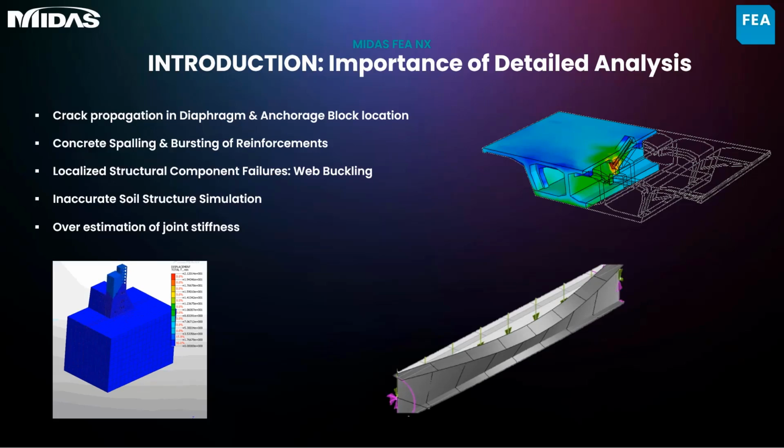Inaccurate soil structure simulation. In Southeast Asian countries like Singapore, where the soil is weak, soil structure interaction significantly influences design forces. Modeling multilinear soil springs often is insufficient to replicate the exact site conditions, and hence modeling the soil itself is always recommended.